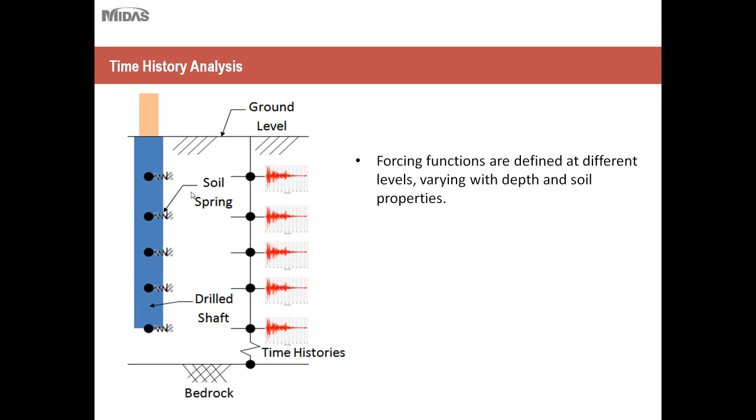Essentially, what a soil spring does is simulate the damping or the vibration acting on your structure. For example, if you subject this pile to a seismic loading, it's going to oscillate, and depending on the type of soil it's pressed up against, those oscillations vary, which relates directly to something called the damping ratio. The higher the damping ratio is, the more stiff or solid your soil is, and the more it resists seismic loading. But the lower your damping ratio is, the weaker it is, and the more susceptible it is to failure and high oscillations.